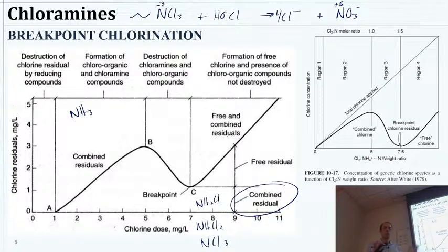So practically speaking, how much chlorine do we add to do a real disinfection in practice? Depends a little bit on the situation, but usually we will have a setup where we are applying more than we expect to keep in a distribution system. So we will provide a higher dose, and what we're going to do is dose based on the residual. So we're not going to dose based on how much we have to add, but rather dose based on how much we are achieving.